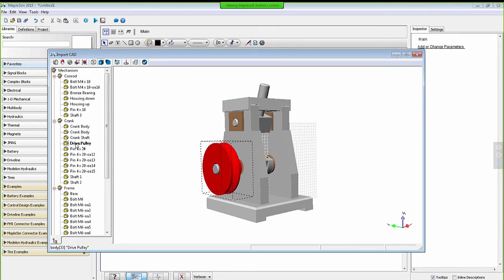You'll notice here that I've only got the bodies or components. I don't have any coordinates that I can attach to. And obviously when I bring this into MapleSim to do a dynamic simulation, I'm going to want to put constraints, so revolute joints and things like that, between the actual bodies. To do that I need to place some coordinates. If this had been a SolidWorks file and I had SolidWorks on this machine, we would be able to pull in the coordinates that the mates were between in the SolidWorks file. But if I'm pulling from a STEP file and I don't have a CAD tool on my machine, I can still get the kinematic information, the bodies and things like that, but I just don't get the coordinate pieces.